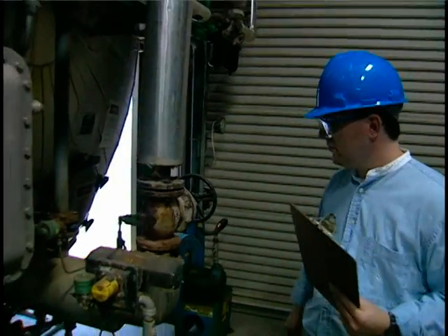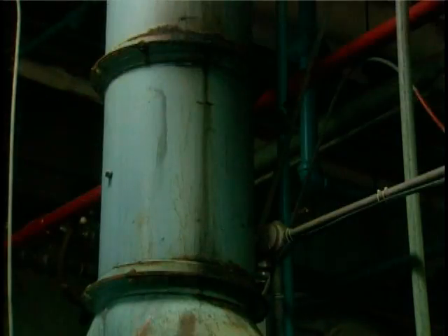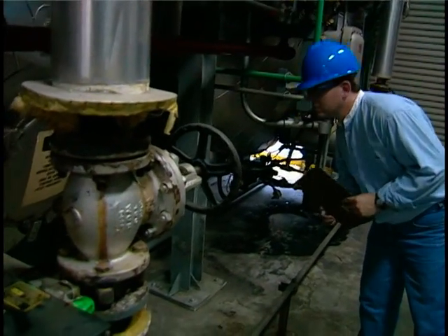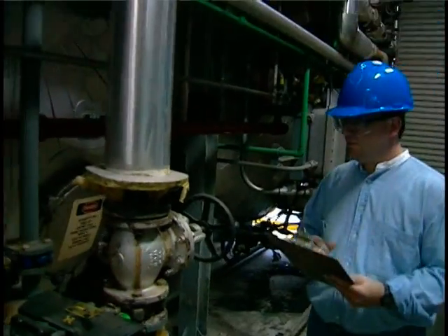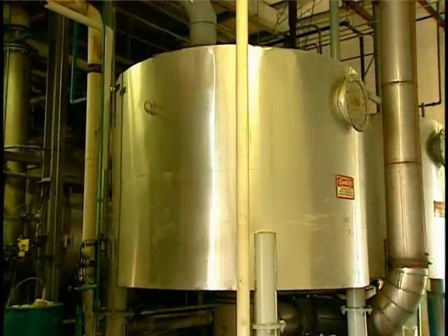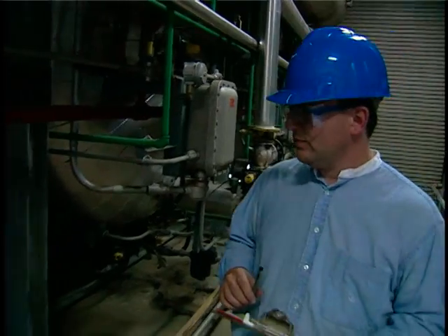Finally, the physical condition of the adsorber system should be evaluated. Corrosion of the adsorber vessel and ducts can be caused by the formation of acid compounds in portions of the unit. The most common areas of corrosion include the bottom of the vessel, where liquids can accumulate, and the outlet ducts, where moisture is present during the purge cycle.